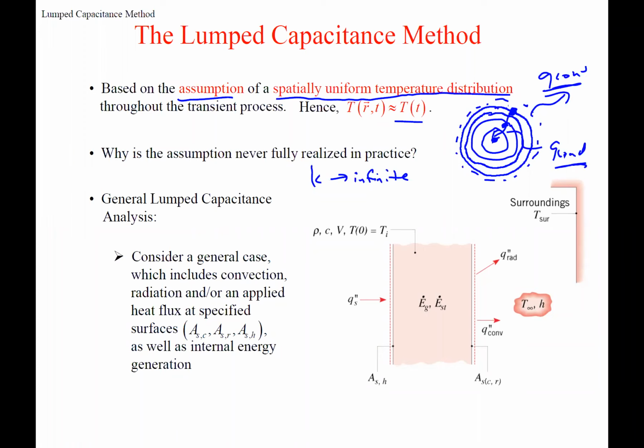Well, we're going to be looking at it as a ratio of conduction versus convection, or whatever's happening on the outside surface. If the conduction inside is happening very rapidly compared to what's happening on that outside surface, then we can neglect the influence that conduction would play on the temperature change with time, and assume it's basically like an infinite thermal conductivity. And we'll talk about when we can say that in a second, okay?